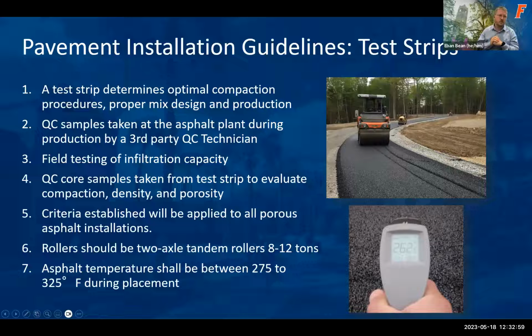It's really important to do quality control by taking samples and analyzing those from the installation site. To think about this, it is going to be put down and be used for decades. So it's important that you take the opportunity to do field testing of the porous asphalt so that water can go in, but also taking cores and analyzing them in the lab by a third-party system.